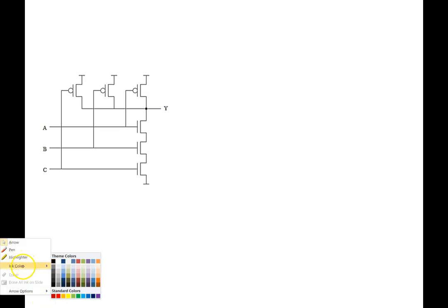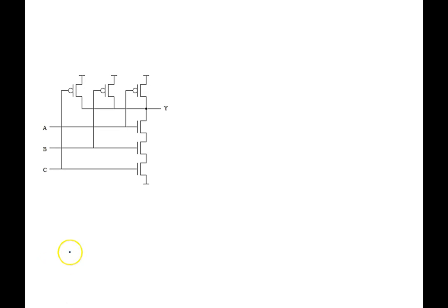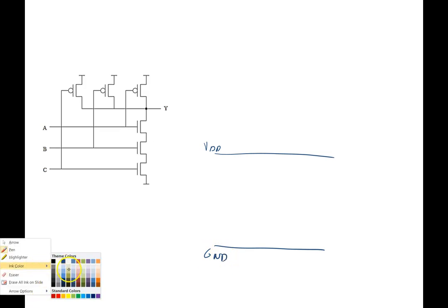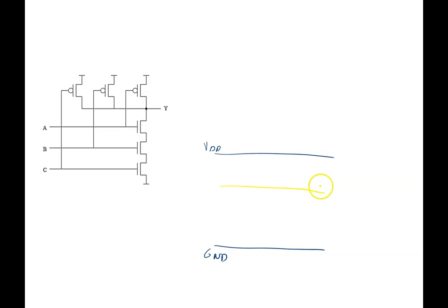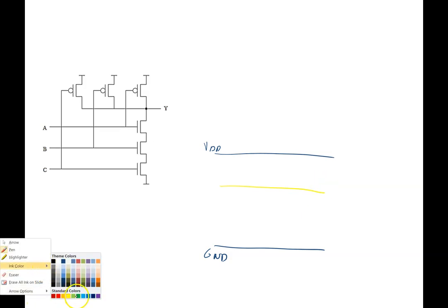Now what if it's a 3-input NAND gate? There have to be 3 polys crossing over the active area.